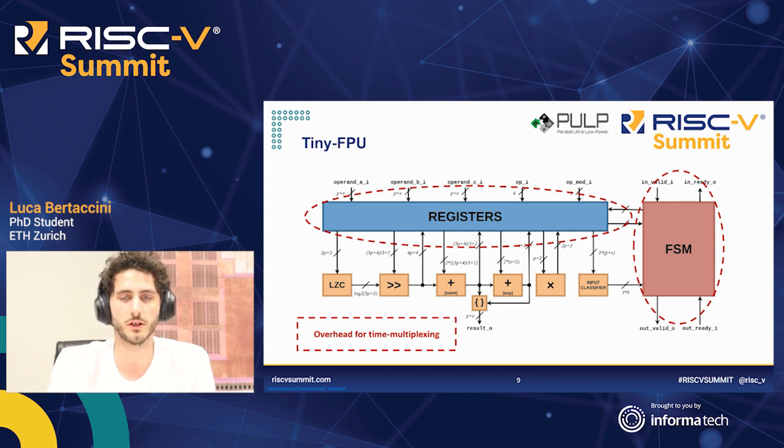Since we have this multi-cycle execution, we could also reuse the components. So as in the schematic, we had just one large multiplier. The other one in the figure is the small multiplier. We had just one large adder for the mantissas, and one small adder for the exponent. We didn't have, therefore, to have multiple components.